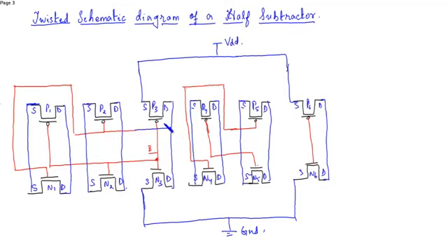So you have to place a contact over here. So just draw like this so as to just specify that there's a poly contact here. Okay. So this is B and this is B bar. This is connected to ground and this is connected to A bar. So that we'll see later on.